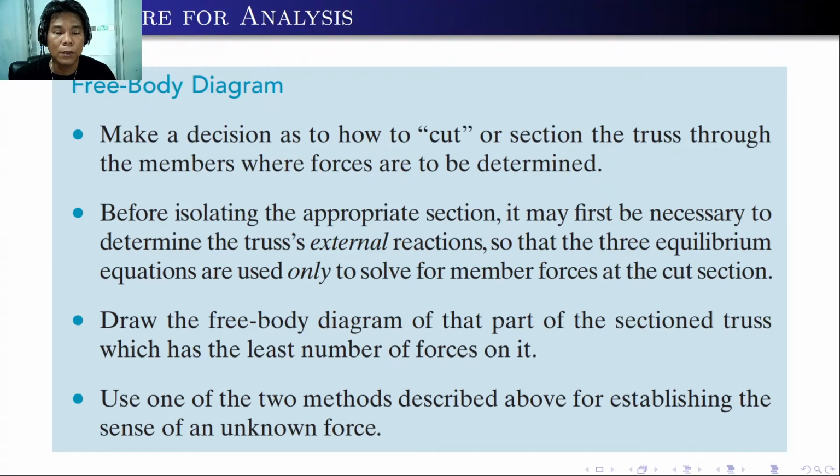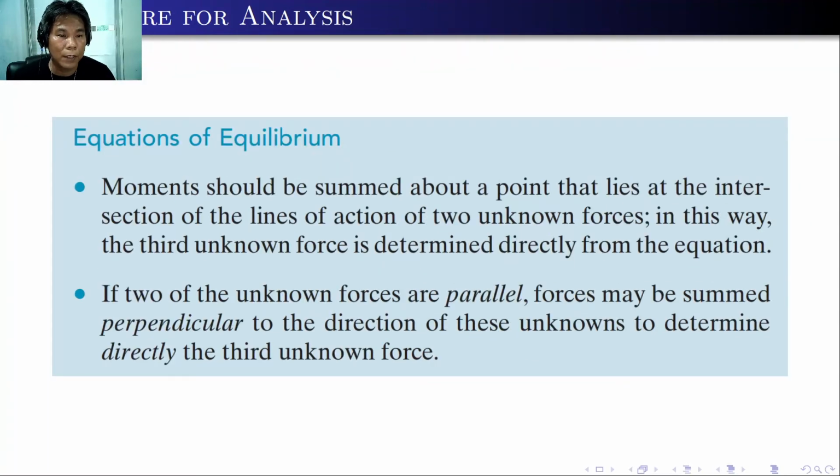Then draw the free-body diagram of that part of the sectioned truss which has the fewer number of forces on it. Use one of the two methods described above for establishing the sense of an unknown force. For the equations of equilibrium, there are two steps.